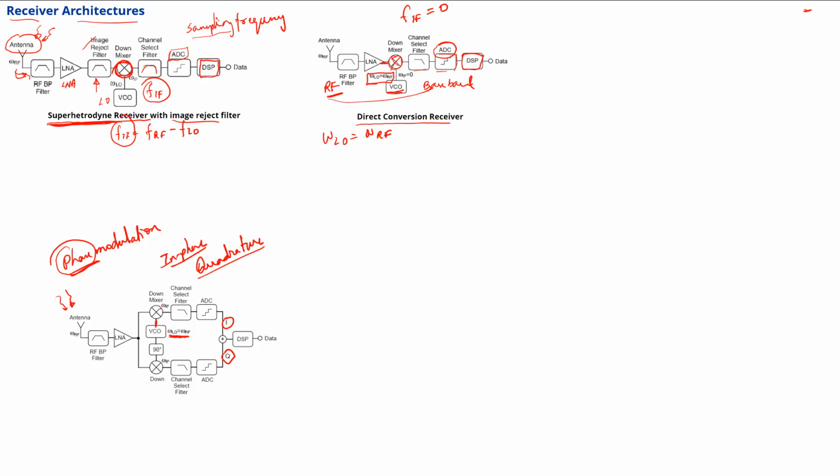One directly connected to the RF input, the FRF that comes in here. You mix that directly with the output of the local oscillator. The second, quadrature component is when you phase shift the local oscillator by 90 degrees, meaning that if this were to be a cosine signal, then after a 90-degree shift it's going to be a sine signal, a sinusoid.